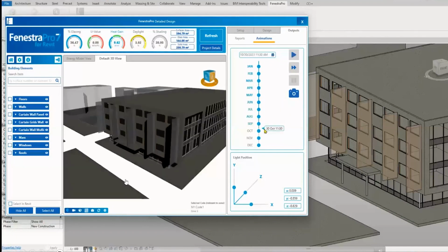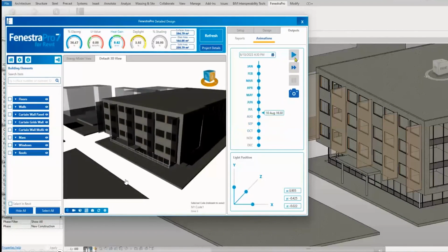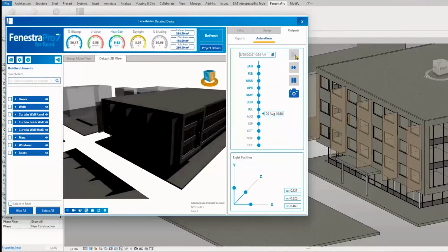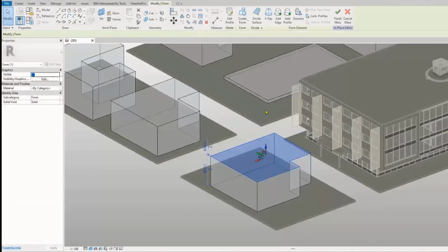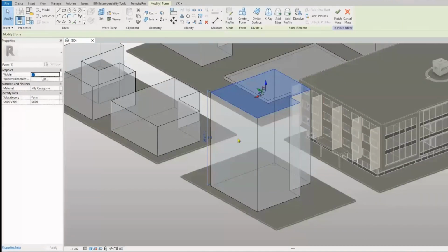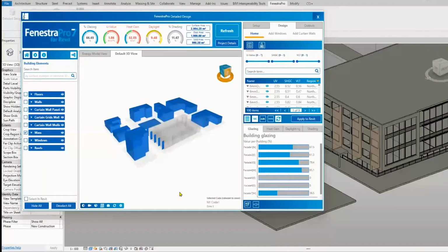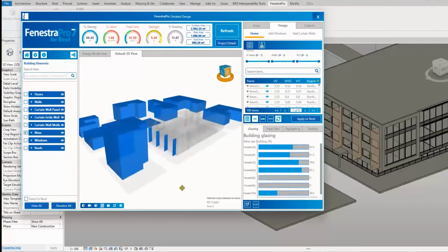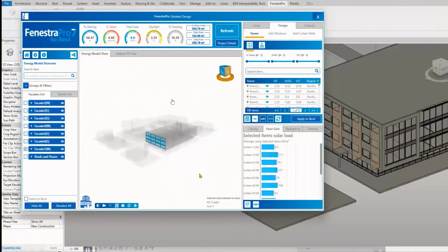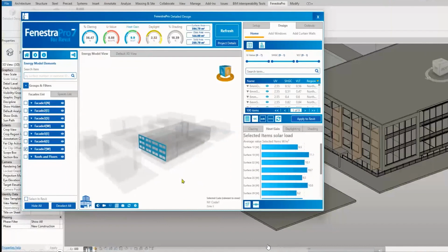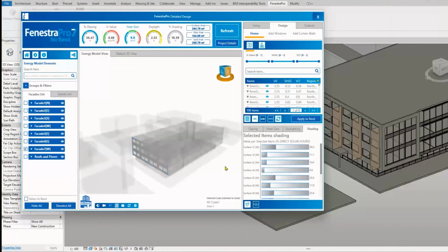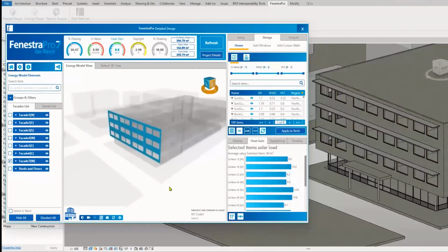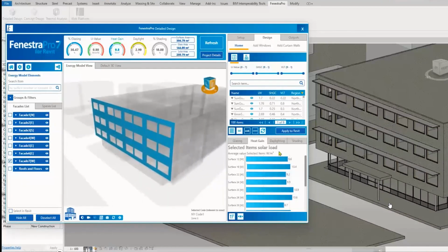We can look at that as a visual in terms of that shading, I suppose that shading analysis, or that shading animation. You can capture different aspects. You can look at the impact of surrounding buildings and how that will play onto your heat gains and your daylight of given surfaces. So there's quite a lot we can do around that shading in order to optimize and to control the impact and understand the impact of surrounding buildings as well as self shading.